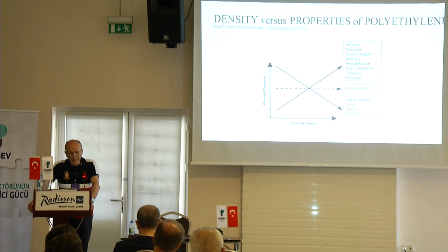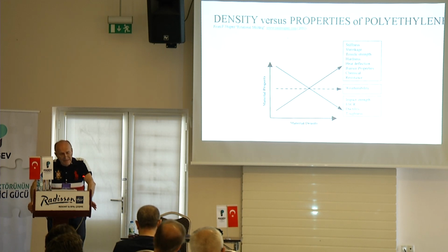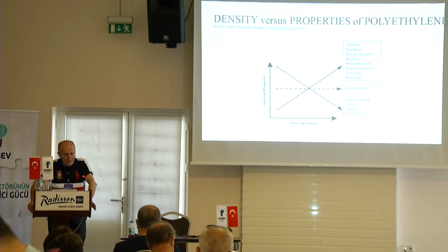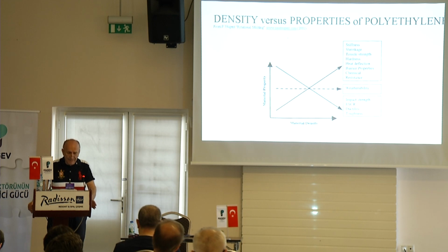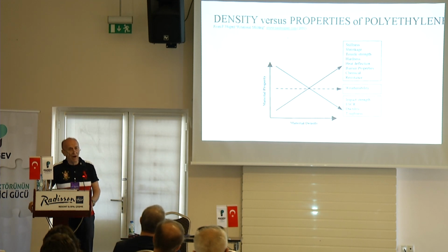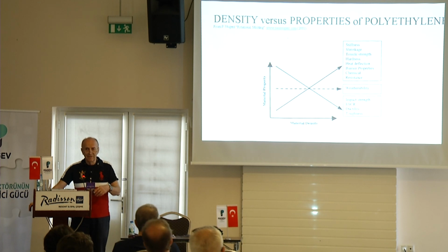Well, you should remember just one thing: density versus material property. As density increases, various properties such as stiffness and hardness would increase. However, some other things like ESCR, environmental stress cracking resistance, drop.